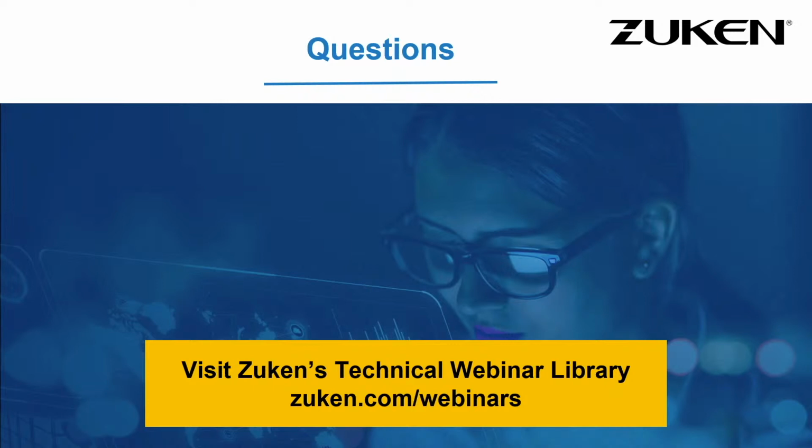Okay, we have another from Paul, and he's asking, I saw in the demo a cross highlight with CATIA in settings. What is that for? Correct. So yes, for this particular version, you do have capabilities of cross highlighting. What that means is if you bring in a CATIA model within the E3 3D Transformer and you have your CATIA opened up in the background, anything that you select in E3 3D Transformer will highlight in CATIA. So there's this cross highlight connection between the two tools.